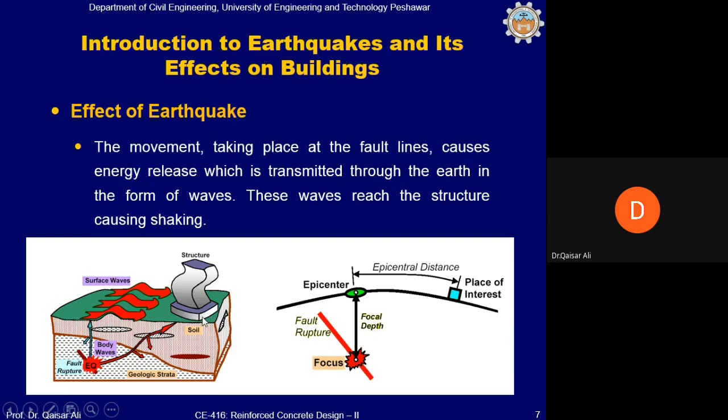When the foundation moves, the rest of the structure cannot move along with this movement due to inertia. Due to the inertia, the upper part of the structure lags behind this movement of the ground or foundation, which induces stresses in the structure. It is these stresses which cause bending moments, shears, and other forms of effects in the structure. The structure must be capable of resisting these stresses, otherwise it may collapse.